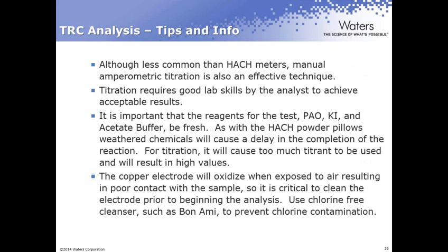When you're doing that, use a chlorine-free cleanser, such as Bon Ami cleanser. The reason you want to do that is to prevent chlorine contamination. Most other cleansers, like Ajax or Comet, contain chlorine, and you don't want to contaminate your electrode with chlorine. But you do need to make sure, in order to get good contact between the electrode and the sample, that it's cleaned.